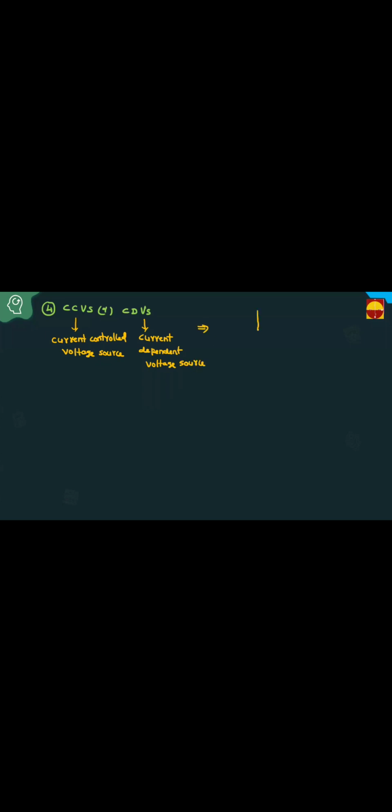It is a voltage source, and voltage source means plus minus. Some constant K4 times the controlling current, so you take IY, where IY is some current in the network at any branch. Clear? Next. This is the current controlled voltage source, which is also linear. Linear dependent sources are available.